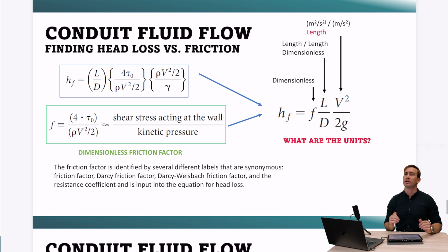You can see that the pipe roughness coefficient for all these different materials varies. So if we look here, some of the rougher materials, for example, like concrete, have a very high coefficient, relatively speaking, for a friction factor when we compare that to something that's a lot more smooth, like, for example, glass or plastic. When a pipe is considered smooth, we say that the value of the sand roughness coefficient is actually 0. Now, what is all of this really related to?